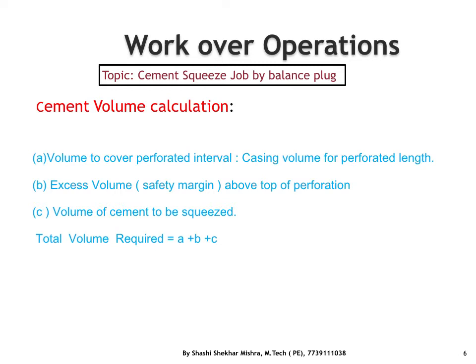Then we need some safety margin above the perforation, which is normally 50 to 100 feet above the perforation interval.